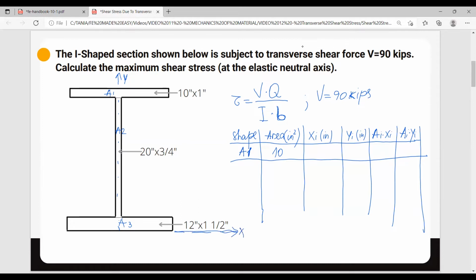Okay, so knowing that I'm going through the middle, my x axis actually goes through the middle because the center of this shape is right on the y-axis, so the x is equal to 0. Now the y equals this distance here, right? There you go. So this is going to be 1.5 plus 20 plus 0.5, and that equals 22. It's 20 plus 1.5 plus 0.5.